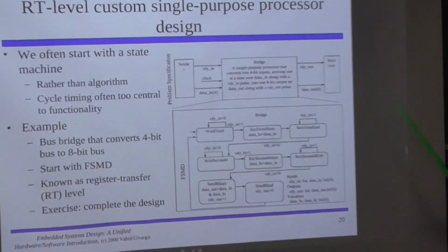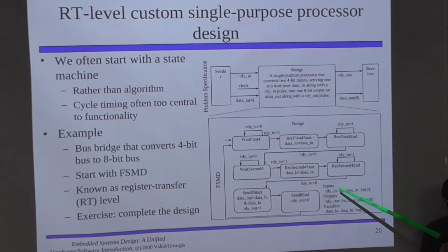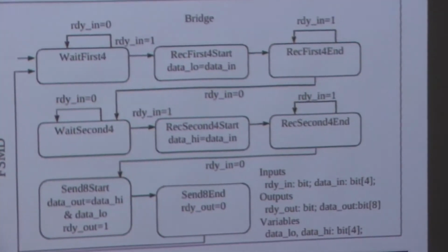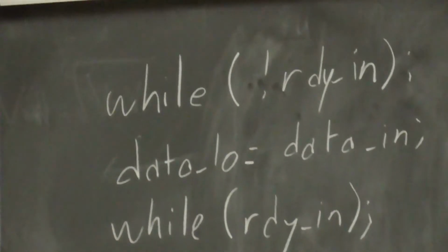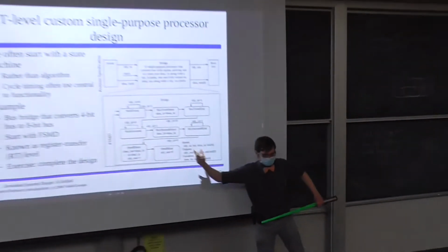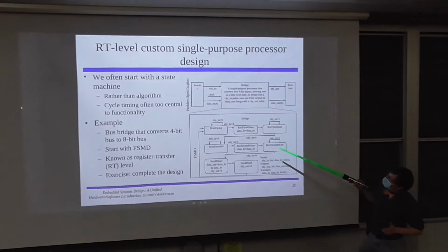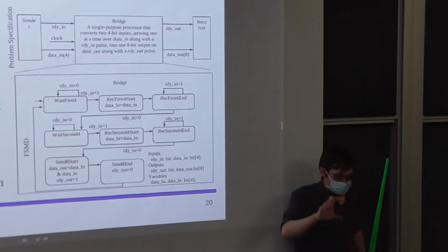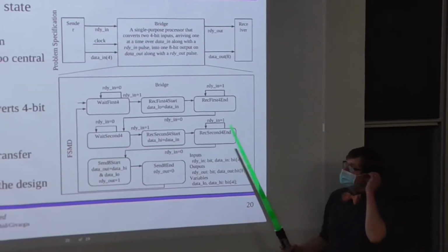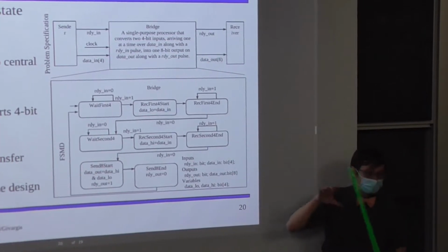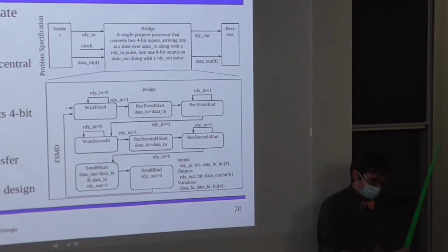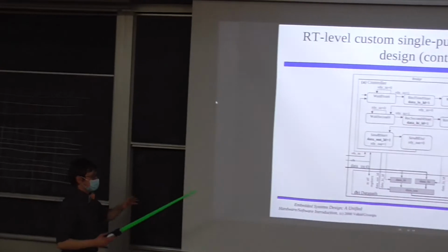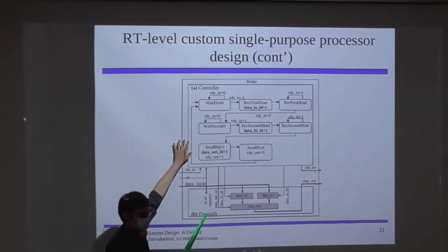Our objective is to design hardware that implements this program without needing something that we can program with C. Right? Yeah. That's the whole point of the single-purpose processor. So our first step, since we want to break this down in terms of state-holding elements and combinational logic, is we need to separate this out, identify those components that are combinational and those components that are sequential. Right? That's step number one.